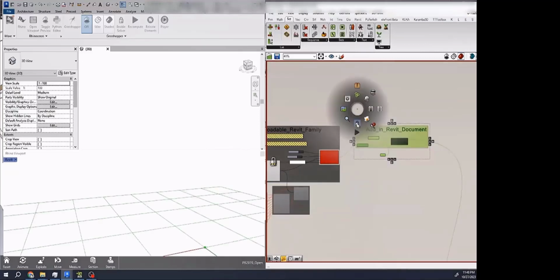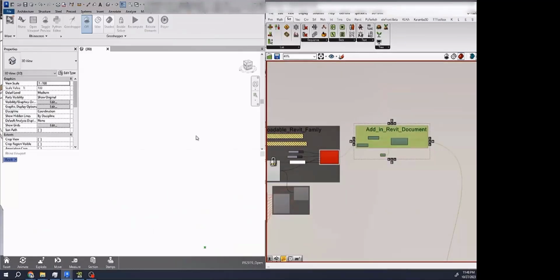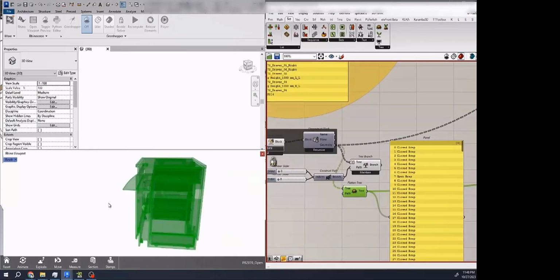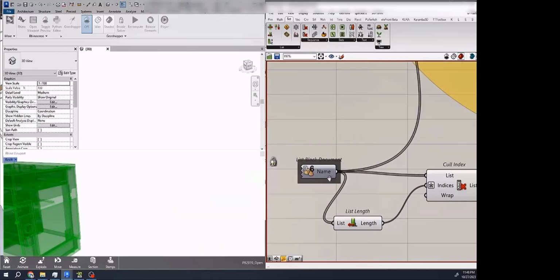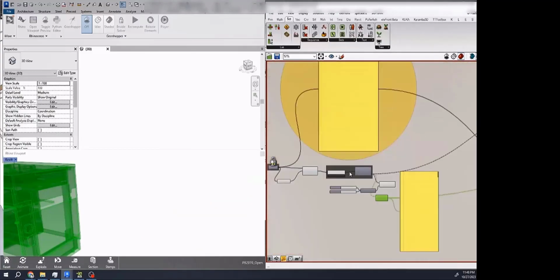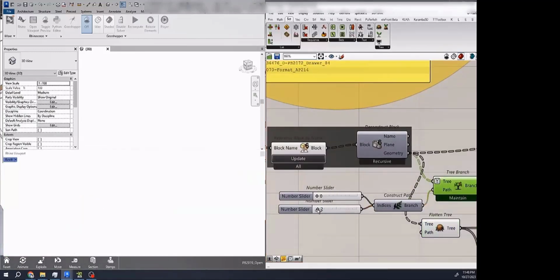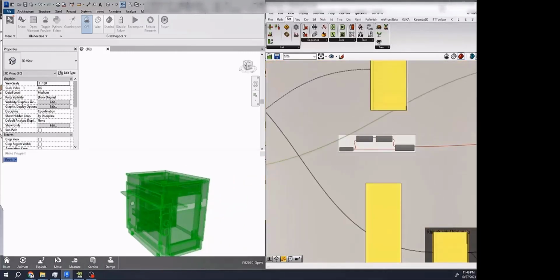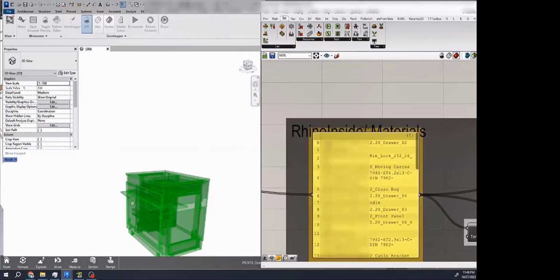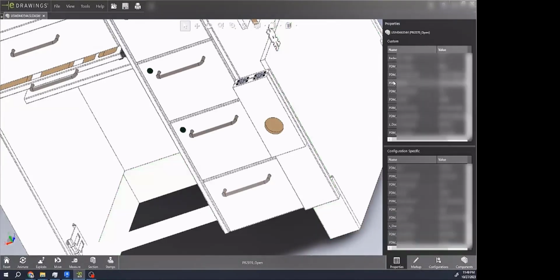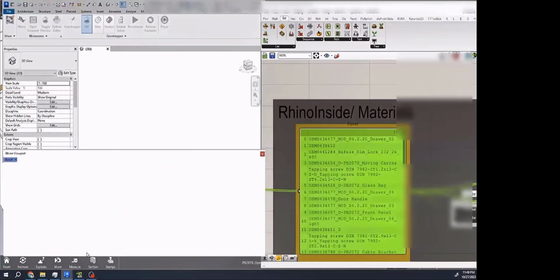But the more efficient way, as I am showing here using Rhino inside Revit, has a really good pipeline. I'm bringing the Inventor model as a STEP file into Rhino, and then, using the Elefront plugin for Grasshopper, we can mine the different parts of this assembly model. We can also read all the metadata from the dataset from SolidWorks. This metadata can be linked from an Excel spreadsheet.